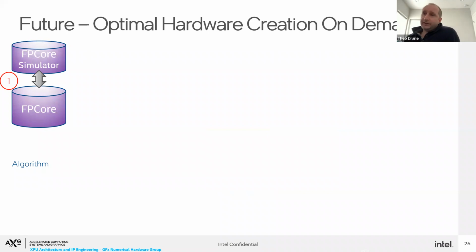So here you would write a machine readable specification, not a lovely Word document. You write your FP core, you can do simulation on it against the reals to see whether you've made obvious stupid errors. So you can do refinement of your FP core. So there is a feedback loop, even at the algorithm level.